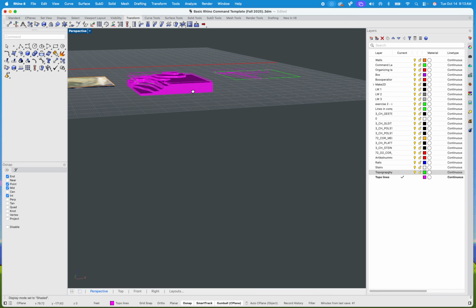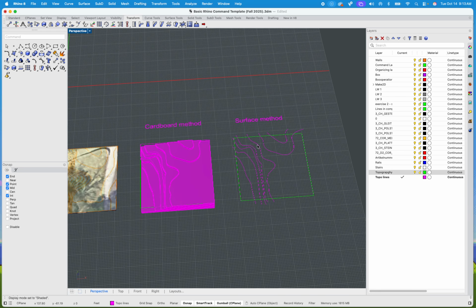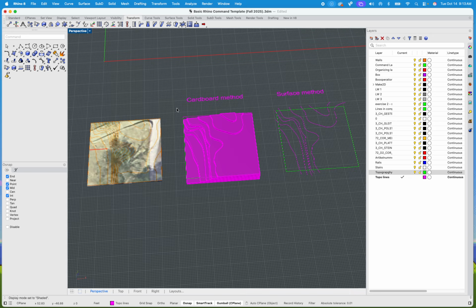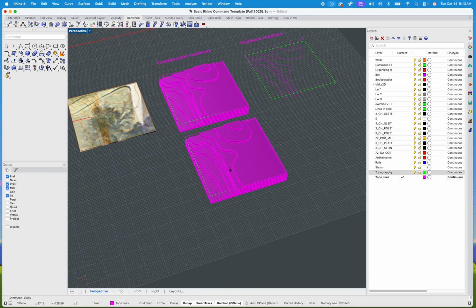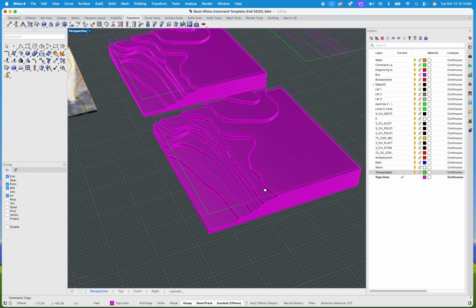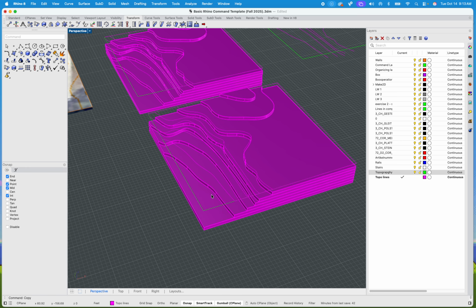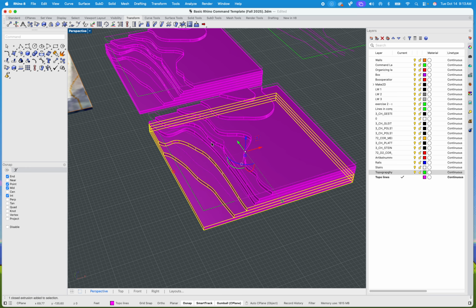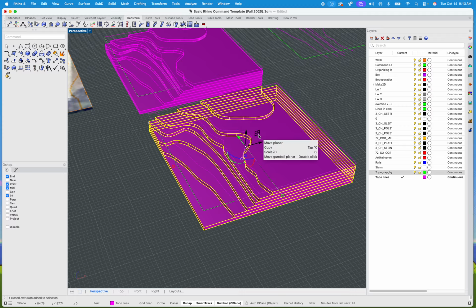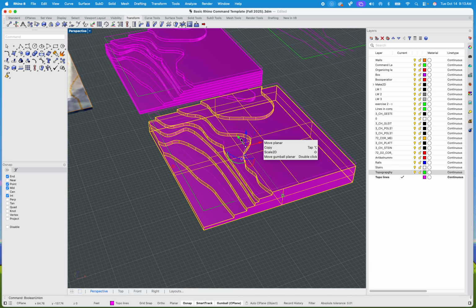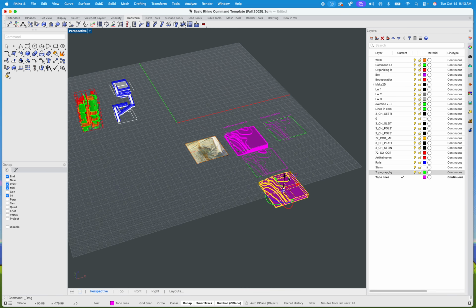To be fair, there's a few things that we can do with that I can use to show off before I go over this part. So let's make a copy, because I may want to keep that one, especially for laser cutting, because it's already isolated pieces, and why not? But another thing that I can do is actually put them together, especially if I was 3D printing. So again, I can take all those pieces and Boolean union, and just like that, I have a whole new surface.